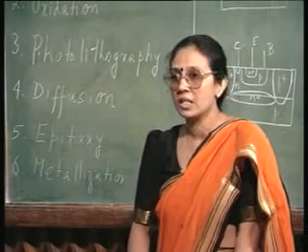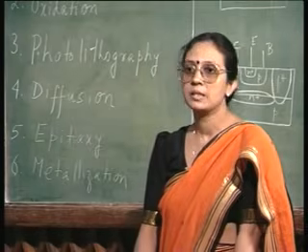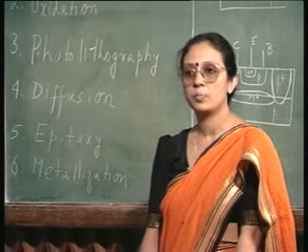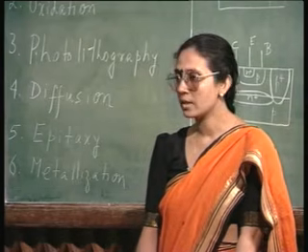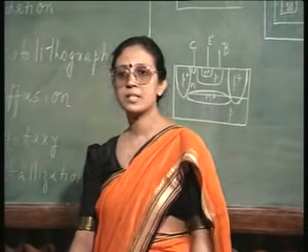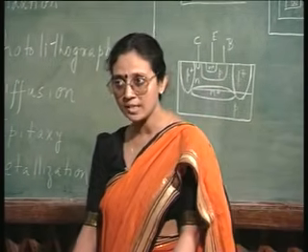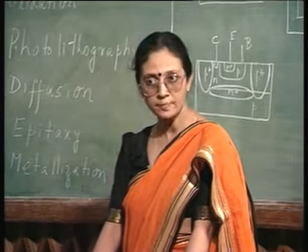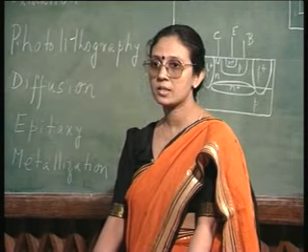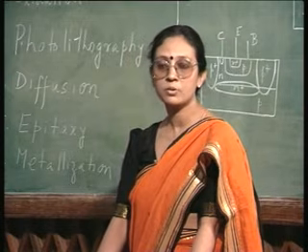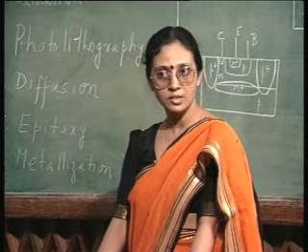So, in a nutshell, very simply speaking, these are the steps you need to realize a bipolar junction transistor. Let us do a very quick recap. We have started with a single crystal substrate, that means we must have some means to grow this single crystal, and then we have subjected it to oxidation, to photolithography in order to selectively remove oxide from certain regions.